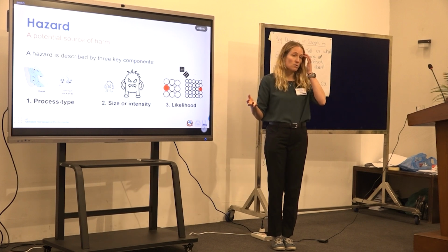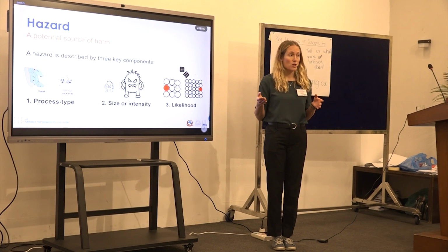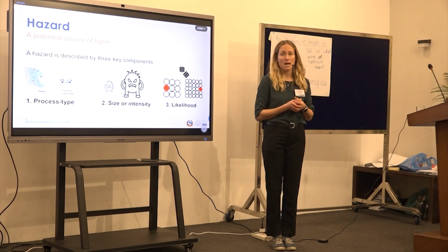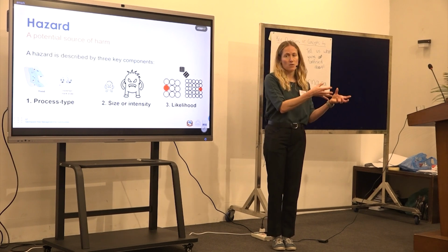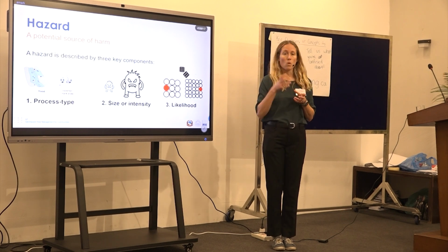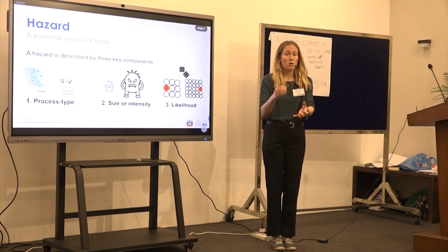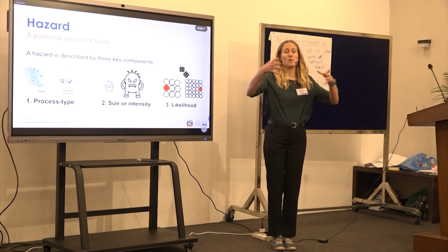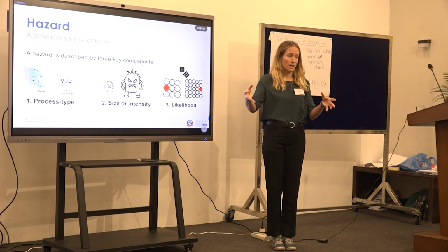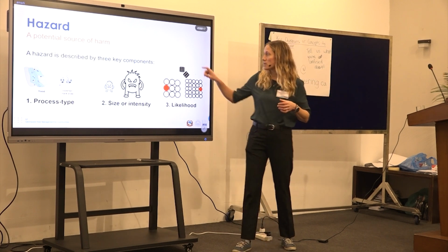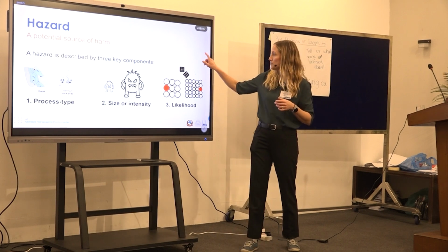And so what that allows you to do is answer a bunch of different questions that can be useful for your mitigation design process. You can say, okay, what is the risk from a 10-year event, or what is the risk from a 100-year event? It lets you understand what is the risk to this building, or the risk for a person in this school. What is the risk for all the people in the school? What is the risk for all the people on the fan, or all the people within the landslide runout area? You can answer a lot of different questions. So quantitative risk assessment can be a really useful tool.